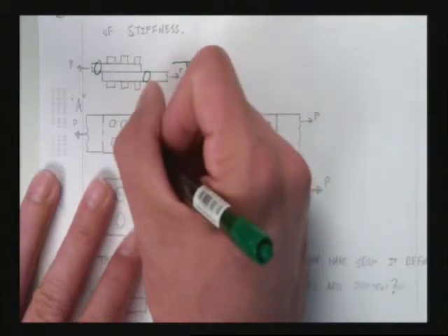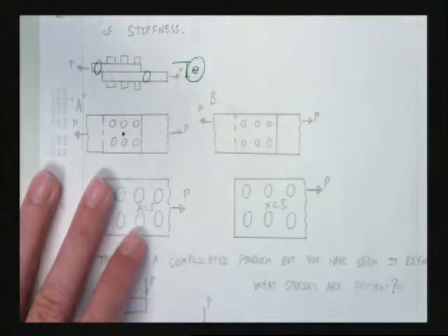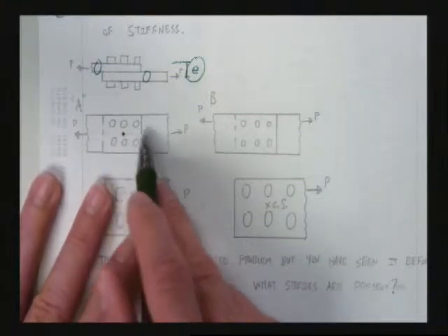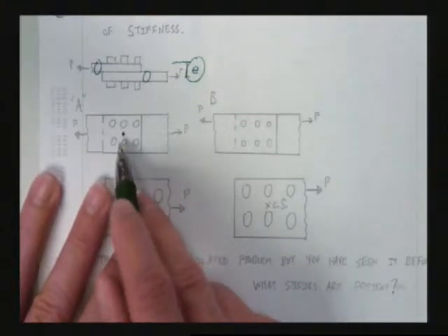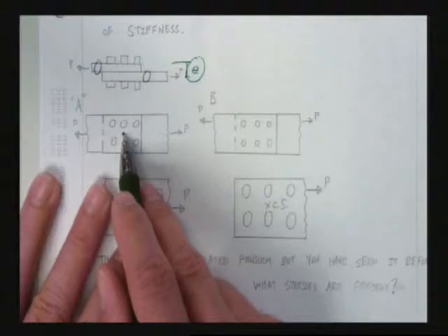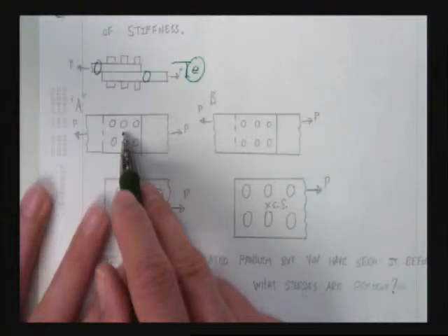I would say that that point right there is the center of stiffness of the connection. Okay? You could almost think of these bolts as, you could find the centroid of these bolts. Right? The centroid of the bolts would be here in the connection. And that used to be what we do. Oh, you should be so thankful that we don't design eccentric connections like we did when I took this class. Oh, man. It didn't make any sense. It was really hard and took forever. And now it makes sense. It's easy and it's short. Sounds like improvements to me, right?